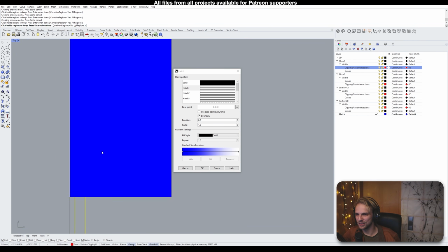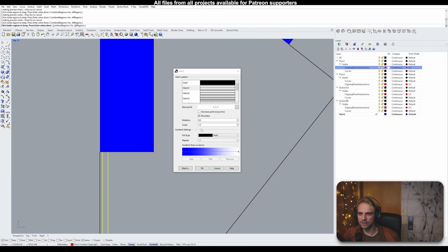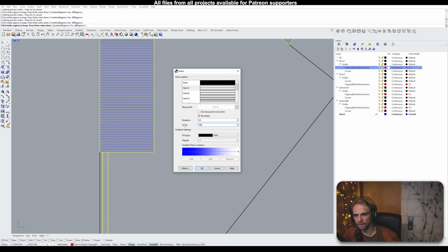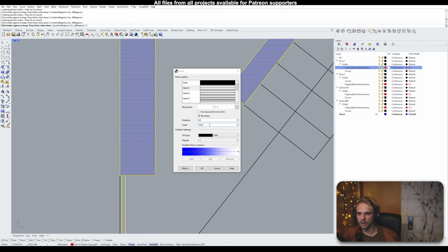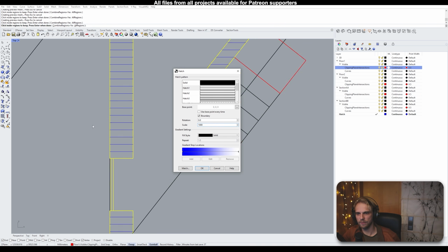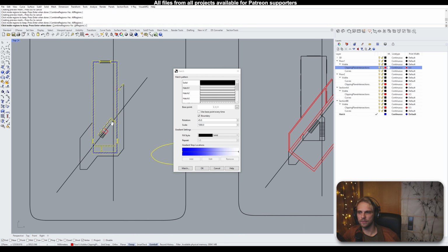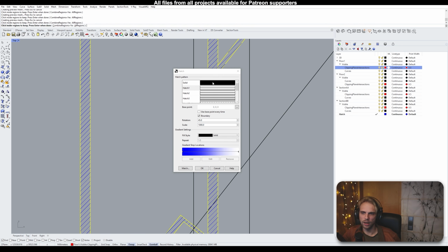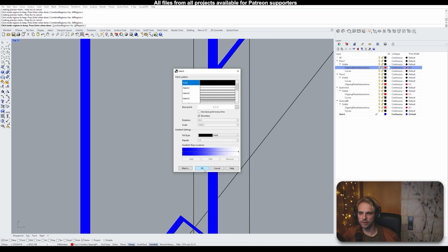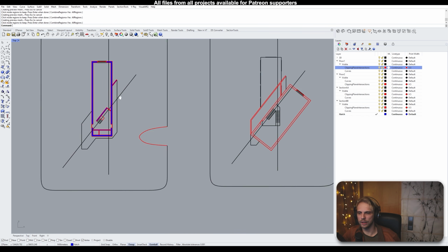But you really need to zoom in. So if this happens, just increase the scale. 100, 1000 actually. And rotation 45, you know, concrete stuff. In this case, I'll just use a solid fill, hit OK. Now we have our hatch.